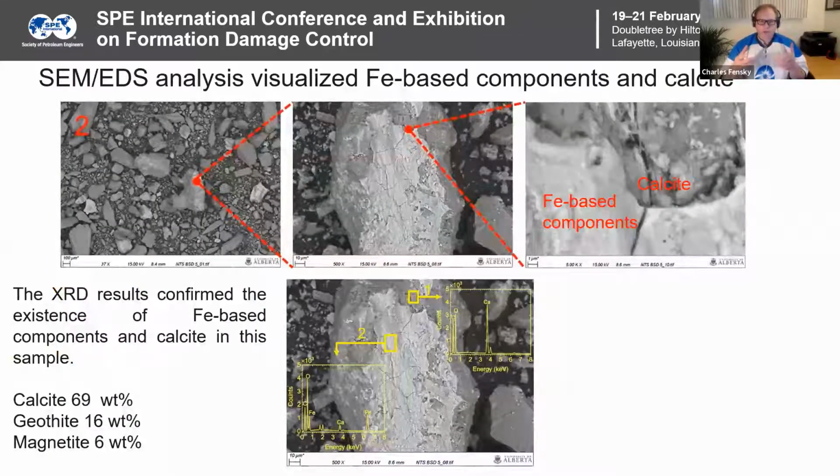So in these samples today, when we pulsed them, we took the debris that was removed from the scale, from the sand screens, and looked at it in much better detail to find out what was the mechanism going on in this process. What we observed in those brittle scales, such as calcium carbonate and barium sulfate, is when you apply those high power shock waves, it tends to generate micro cracks and fractures in the scale itself, really debonding and breaking it apart. You can see that here in the images in the middle, where it affects both the brittle scales that are iron-based, and also in this case, the brittle scales that were calcium-based as well.